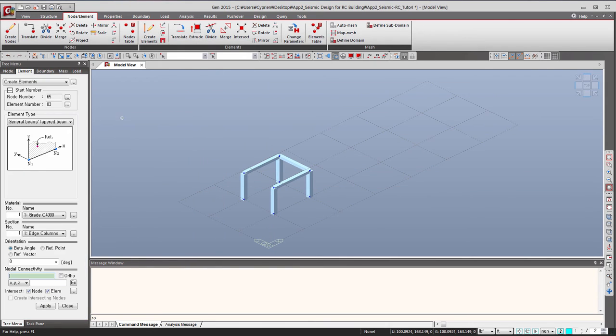So go into create element, and in the element type you have wall element. So let's choose the right thing. So this is a membrane, okay, plate base. The material is okay, there's only one thickness, so it's okay. Okay, so basically everything seems right. So let's click here, and you have to go to select the nodes in the right order, which means like that. First start with the bottom, then select like that all the nodes, and your wall element will be generated automatically.